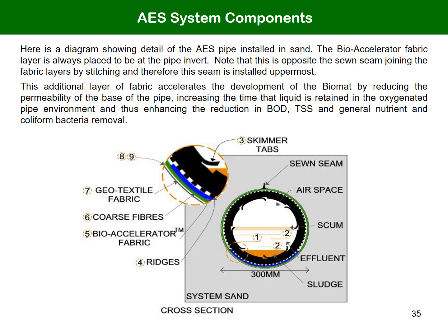Plastic skimmers extend inwards from each hole. These skimmers help capture grease and suspended solids, preventing them from escaping through the pipe perforations. Aerobic bacteria therefore have the opportunity to thrive with the alternation of liquid effluent level.